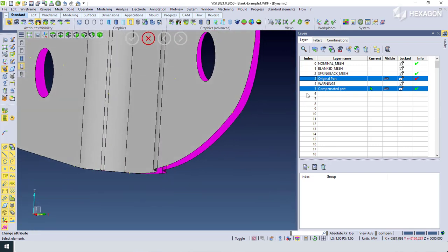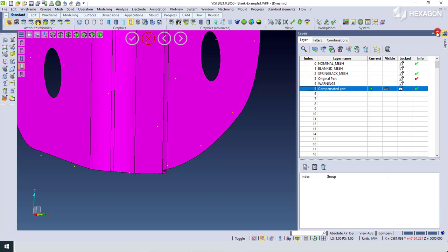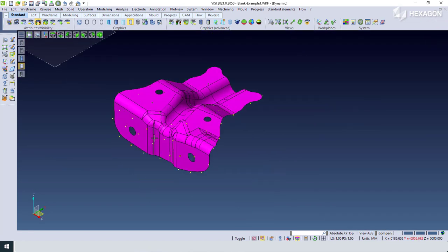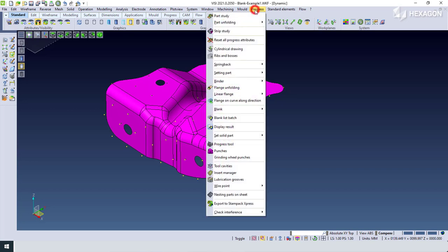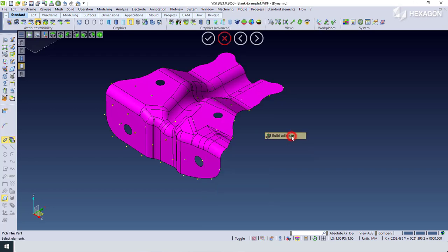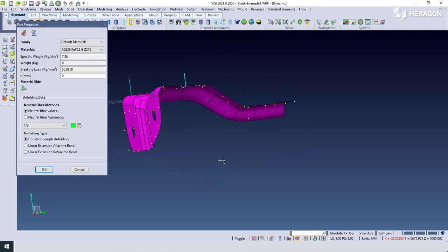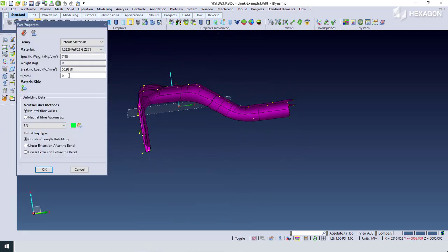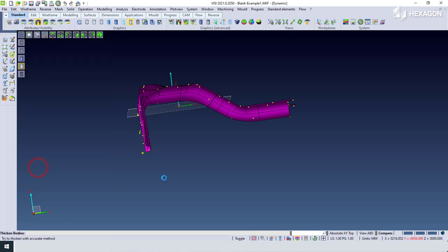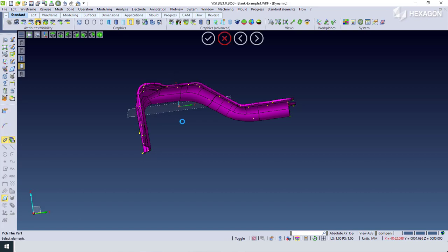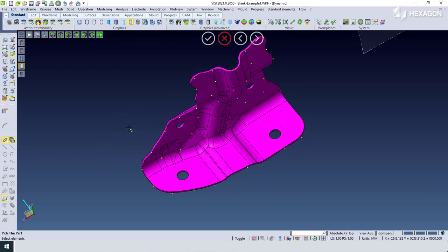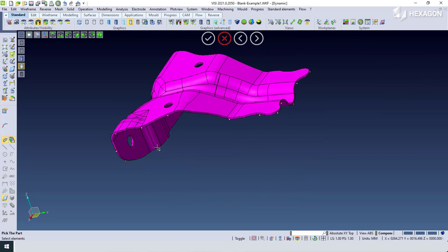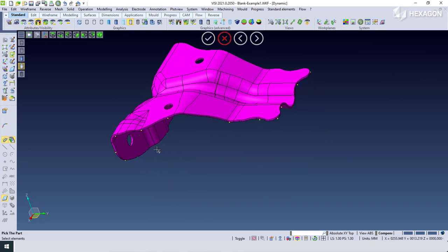And just to show you from the video, this is a surface at the moment, and we can use one of the various tools within Visi to build a solid part. Put a value of 1.4 millimeters. Validating the part, and eventually a full thickness of 1.4 millimeters on there. This is now ready for the next part of the design process.